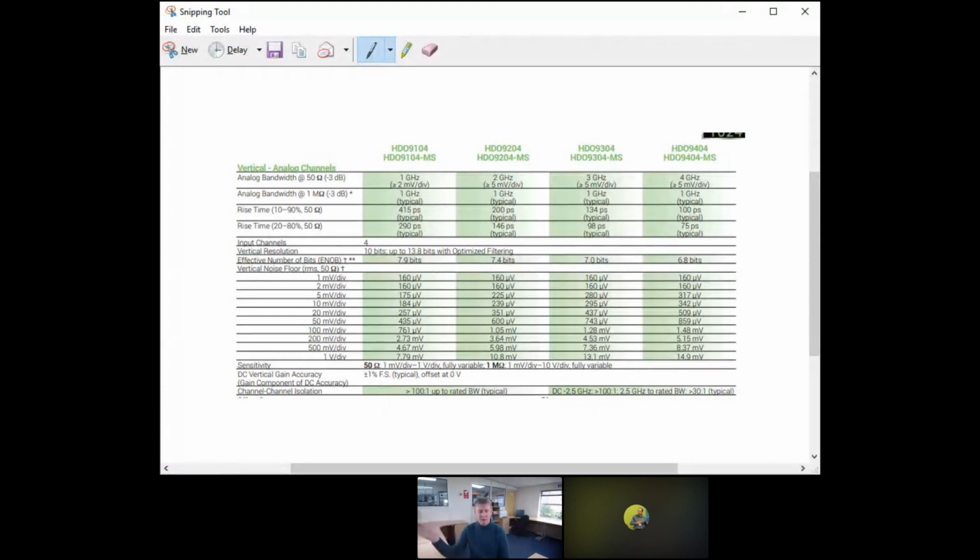So I think it's completely valid, certainly, to make measurements using a scope of absolute values, but it's always a good idea to have at the back of your mind the accuracy that the scope is going to give you. I have a feeling also the accuracy of the scope depends on whether it's not just full scale as well. It's also if you've dialed in to have a very small resolution, like a few hundred millivolts per division, and your signal you're looking at is therefore going off the top of the screen. It comes back to the point you were making earlier, Jose.